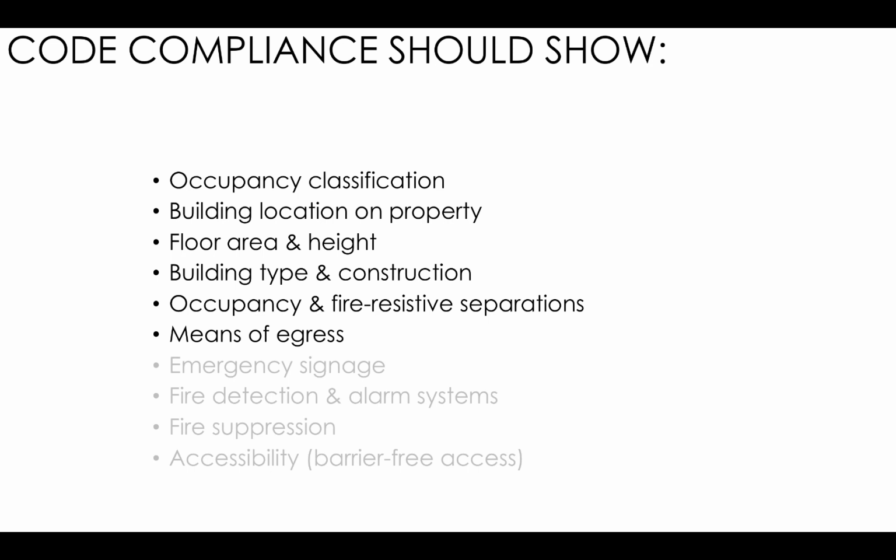The big thing with that is to figure out who the authority having jurisdiction is, so that you know what building code to use. I cannot tell you how many times using the wrong building code is a common error, kind of a rookie mistake. And I won't say it happened to me, but needless to say, it's not uncommon.